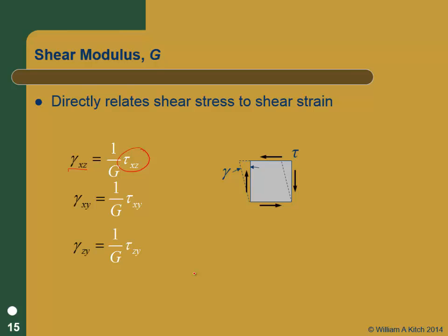So the point of this whole exercise is to give you an understanding of the difference between the bulk modulus and the shear modulus versus Young's modulus and Poisson's ratio. We use Young's modulus and Poisson's ratio a lot in materials because we can understand very easily how they relate to unconfined compression, and they were done early. But for many of our geotechnical problems, the shear modulus is more important.